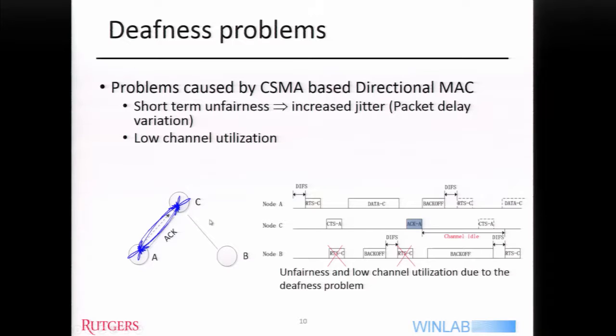Is the power consumption the same when it's in quasi-omni mode versus when it is actually pointing at someone and decoding at high rate? Yes, the power consumption is the same. Probably the power consumption is dominated by baseband processing, not by the radio power.